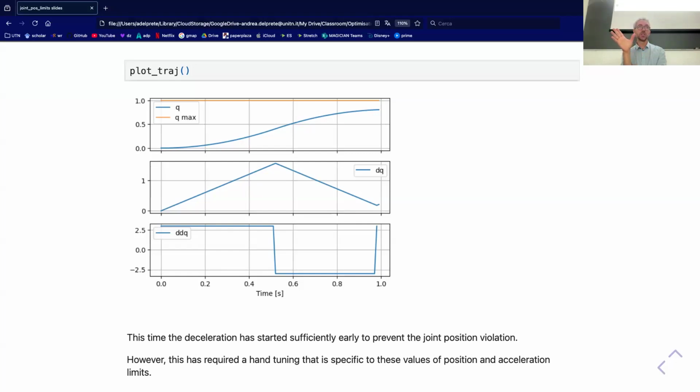But now, since we are doing the so-called reactive control methods, this is something that is very hard to address with reactive control methods because it requires this prediction window into the future to anticipate when it is the right moment to start braking to avoid something bad happening a long time into the future. Okay, this is instead a reactive controller, so it only looks at what happens right now or at the next time step. So it's very short-sighted.